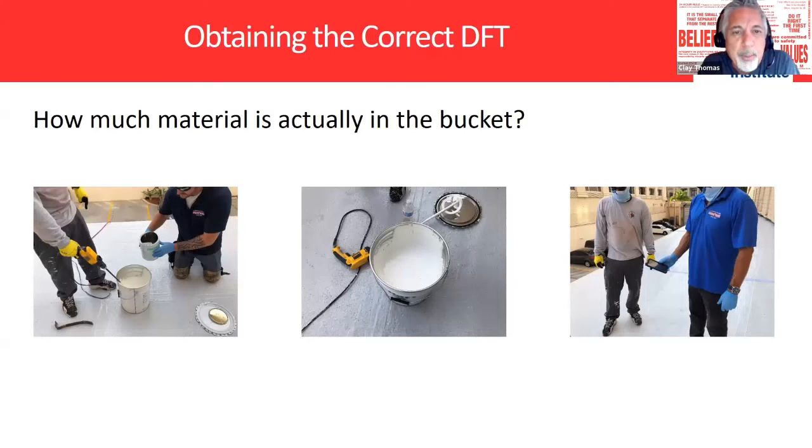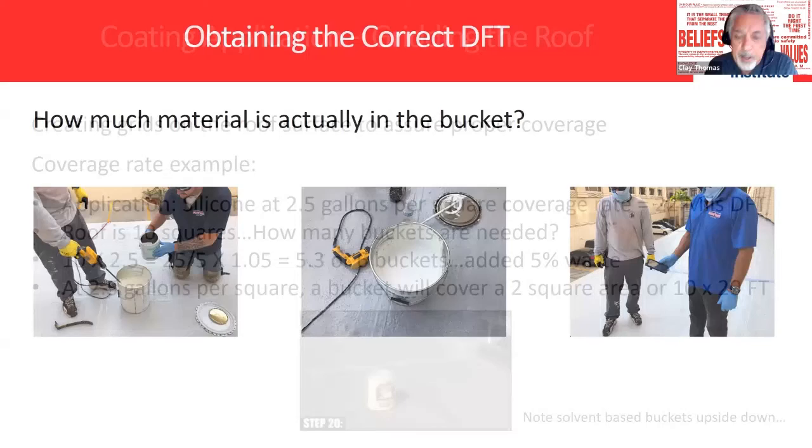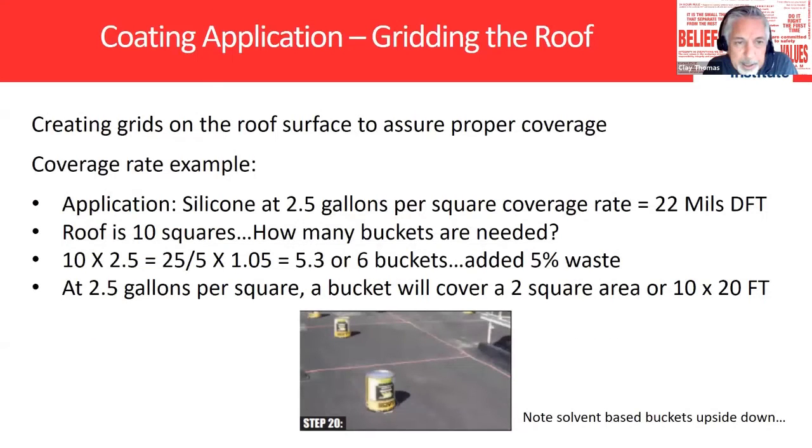And also you want to make sure you have an electric drill, and a hefty electric drill, because of the viscosity of the material. Okay, so it's not latex paint, it's thicker. So you're going to burn your drill up if you don't use a good quality drill. You don't want to use battery operated equipment, because you don't want to be halfway through the mix and have your battery conk out, because it is very specific as to the timing.